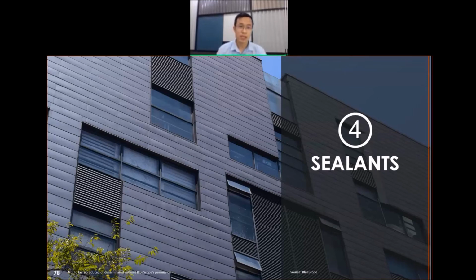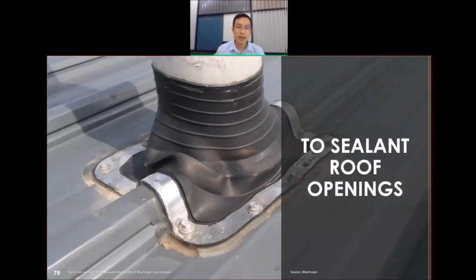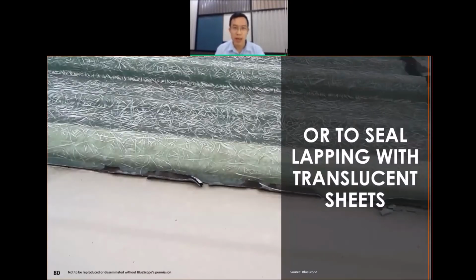Okay. So on to the fourth point, which is sealant. Of course, sealant is something that is really minor and most often unseen, right? Because it is only applied in between the gaps and so on. We know that sealant is typically used to seal any types of roof openings, such as the example shown here, or even to seal any lappings in between the steel cladding and translucent sheet, also to prevent some types of leakages. This can be contributed by the flexibility of sealant.